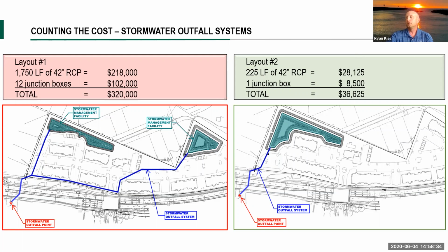But yes, by not having the pond over here in this corner, it's true some of these areas have to be piped farther to get to this other pond. But the pipe carrying the water going into the pond was also much smaller. We didn't have the 42-inch pipes. It would have been maybe 24s or 30s with smaller manholes. So the size of pipe would have mattered too. So there maybe was a little bit of increase in storm sewer costs going into the pond, but nothing nearly what we would have been spending on the outfall pipe. It's a good question.